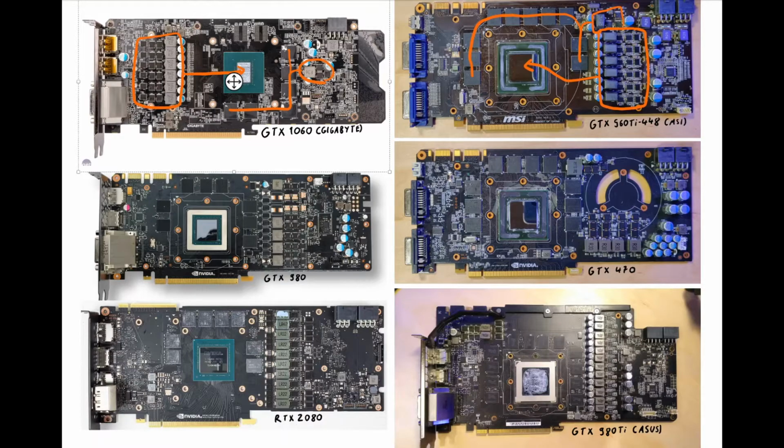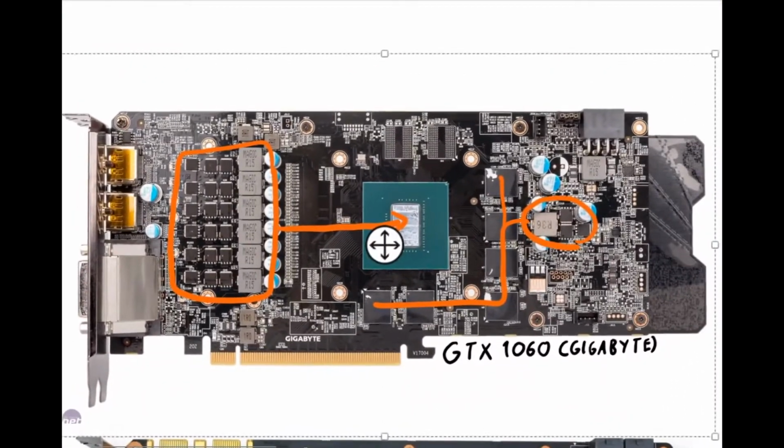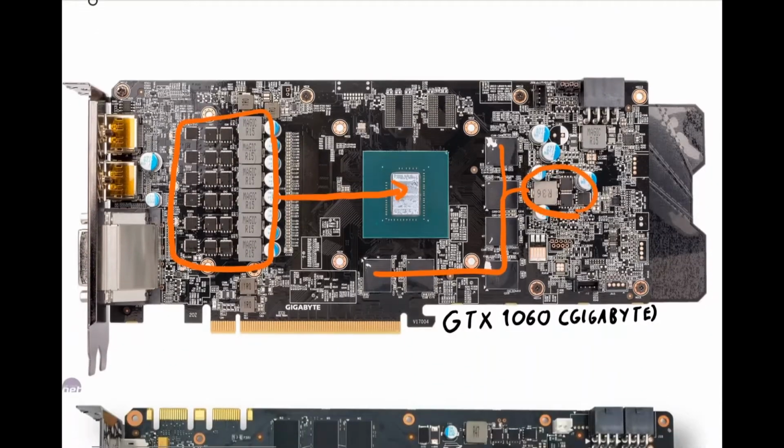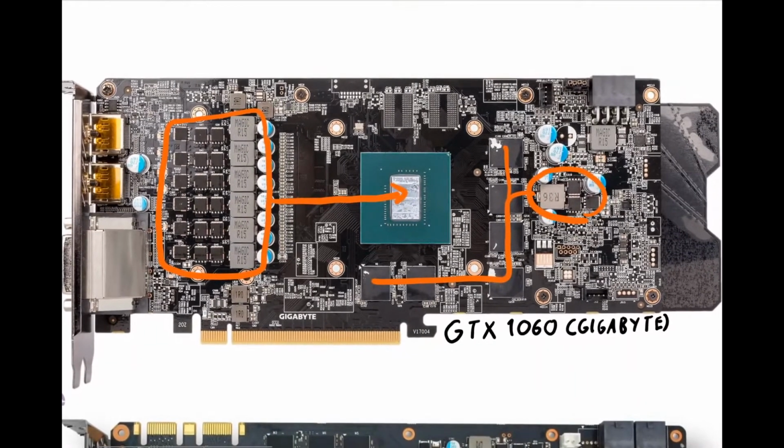But there are cards which use a special layout, like this GTX 1060 here. You will see it on more budget cards, or cards that don't draw that much power, or cards that just don't need that big of a VRM. This one is actually pretty big already, but you can see how far offset from the PCI Express slot this core is, so they have enough space to put the VRM on the left side.